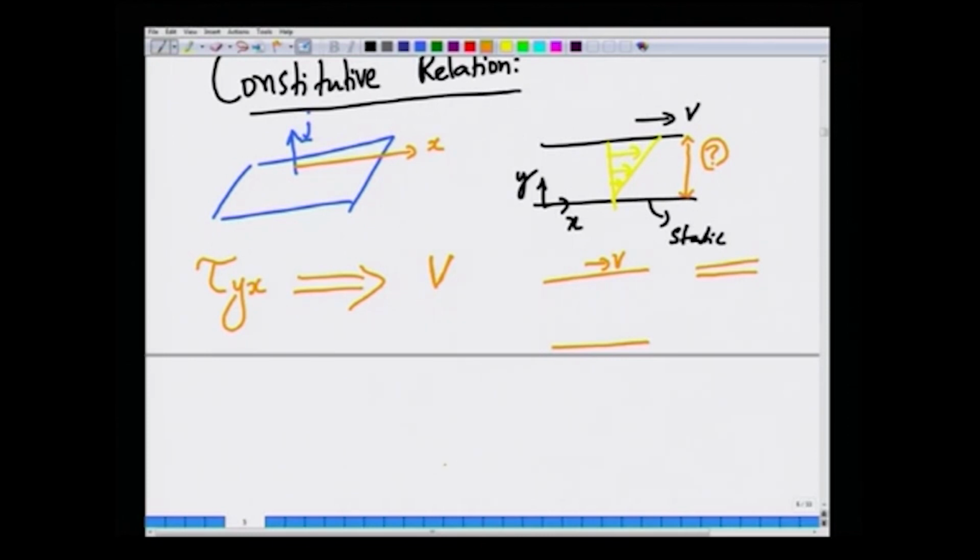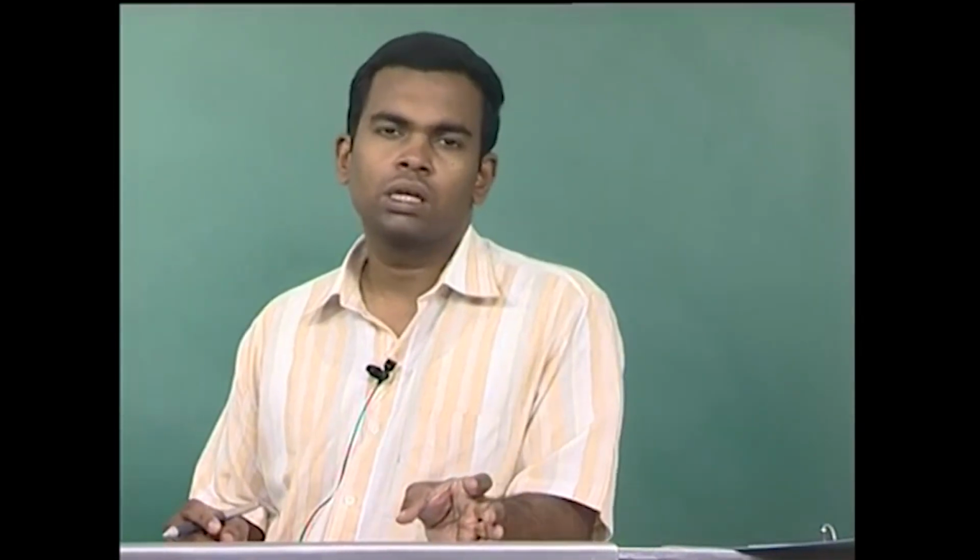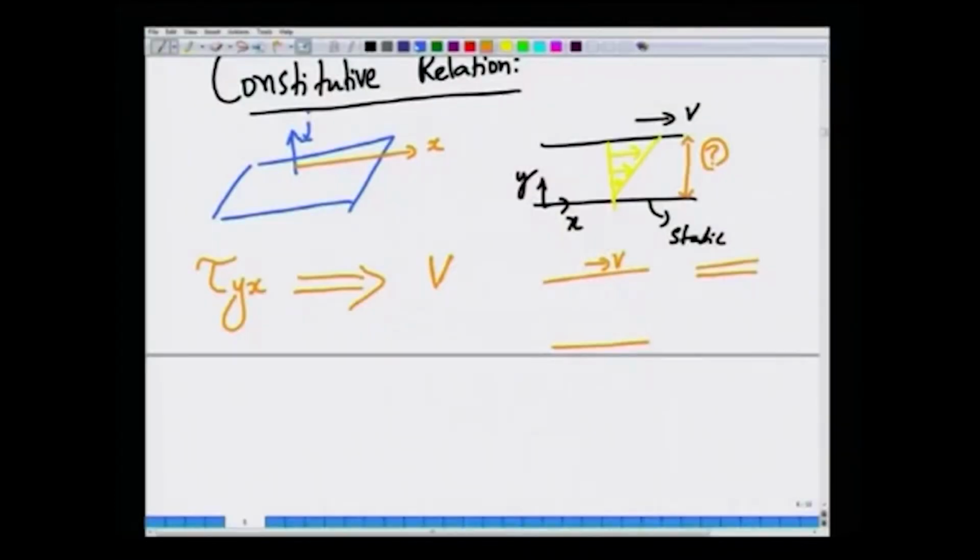Also, from a physical point of view, if the entire fluid moves with a constant velocity, then there cannot be any internal viscous stresses generated, because that is merely rigid body motion. Stresses are generated in a fluid only if there is relative deformation between 2 points, when 2 points move past each other.